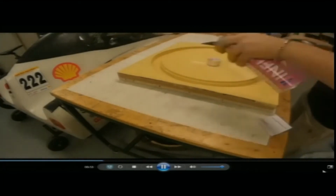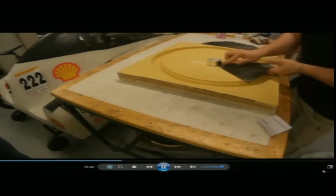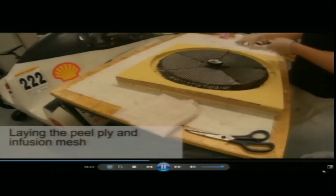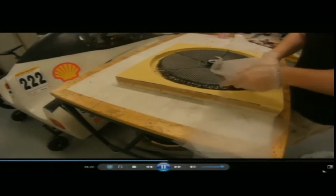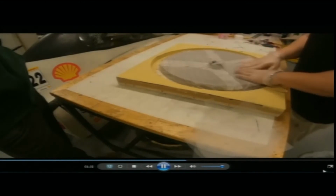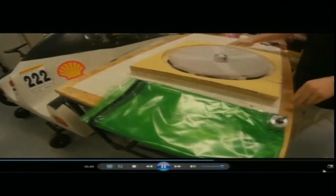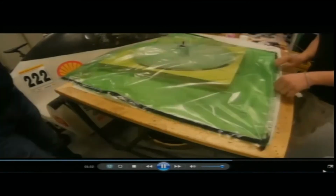So, that is getting done, so that the composite would come out beautifully, and then it is already resin coated. So, now what they are doing is the hand layup of the ply. So, they are cutting, and you can have as many layers as you wish. Okay. At this stage you can also insert the smart actuators, but if you do so you must have the electrical leads there.